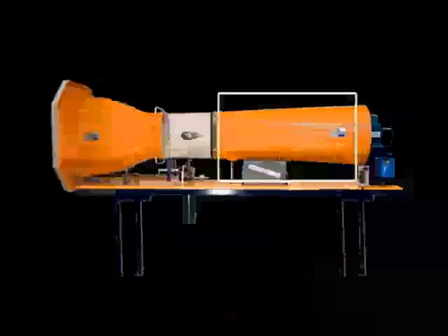A low-angle diffuser at the outlet end contributes to flow stability in the test section. It also increases air volume in order to reduce the airspeed as it exits the tunnel.